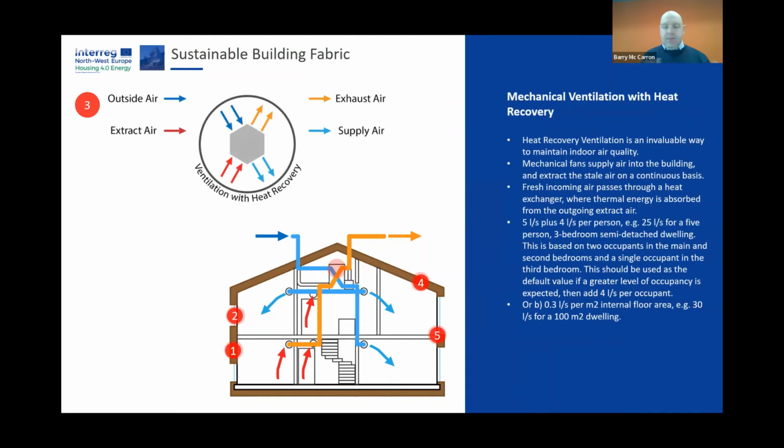The third, or the order is a little bit messed up here, is the mechanical ventilation unit. These are all really sophisticated units now, and our marketplace and supply chain is more than able to deliver them. One of the prerequisites for these types of ventilation units is that they have an efficiency above 75% heat recovery.